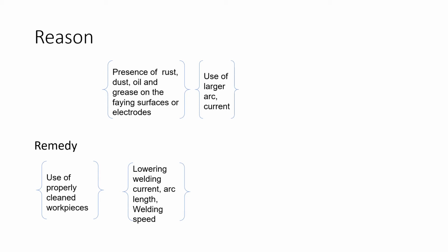So when this oil, dust, rust, etc. remains at high temperature while the welding is taking place and the molten metal is getting deposited over the surfaces, at that time the oil and grease burn, and dust, rust, etc. burn and produce some gases.